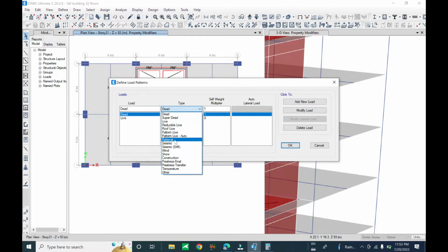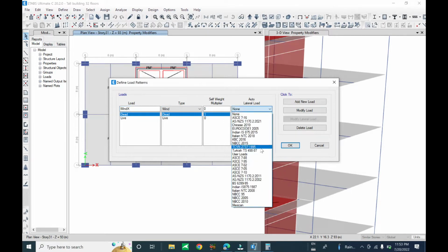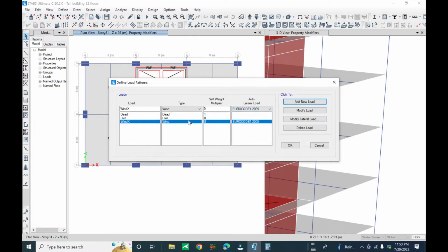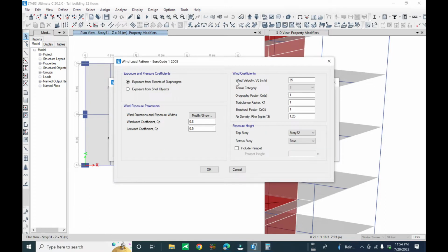for the wind load. This one I call wind direction, change to the 0 code 1, add, and wind in Y direction, add again. Now let's check and modify. This one we use the wind velocity V0, change it to only 28. For the interval 1/50 years, so the probability is around 0.02. The terrain category 2.